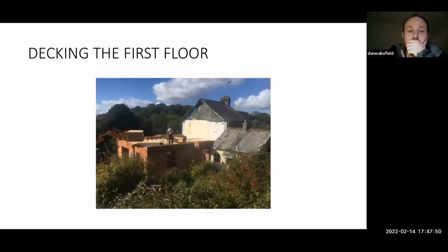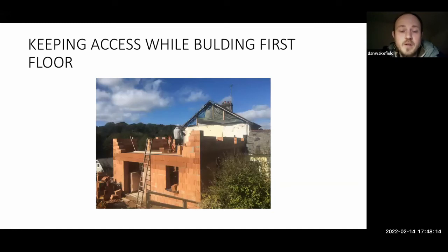So we put the joists in, deck out, and then you can build the next course pretty much off this floor. At this point, we probably should have had scaffolding around. It didn't arrive, but the nice thing is that you can build this all from the inside. And here you can see we've left this wall open at the end so that we can keep bringing blocks onto this level with the telehandler.